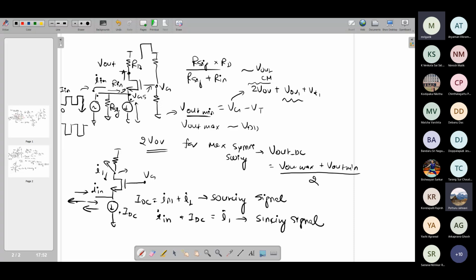All right, and then looking at, say, input impedance. Since it is directly related to RD, we should also be aware that there is going to be a trade-off between input impedance and the gain of this stage, right? Because a good current to voltage gain ultimately depends upon RD, because here the current to voltage gain is directly RD.